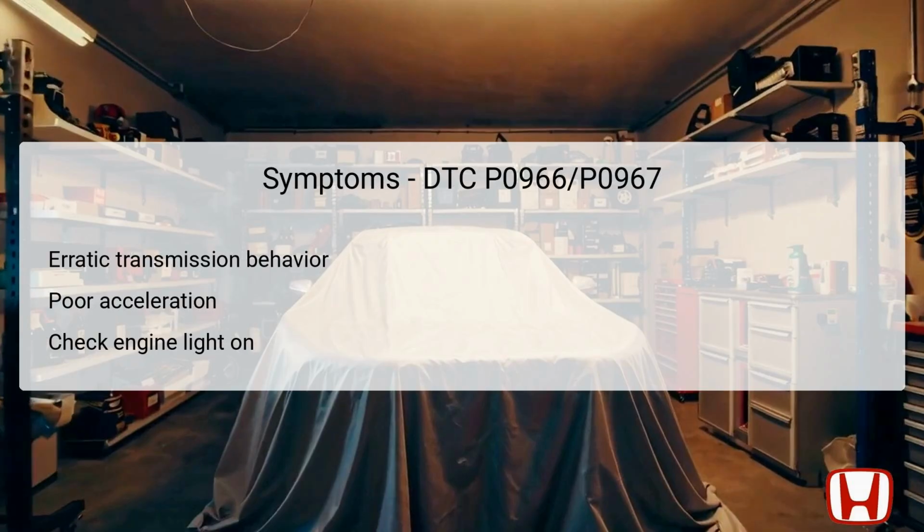Symptoms associated with DTC P0966 and P0967 include noticeable erratic behavior in the transmission, which may manifest as unusual shifting patterns or slippage during acceleration. Additionally, drivers might experience poor acceleration as the transmission fails to maintain the appropriate pressure required for effective power transfer.